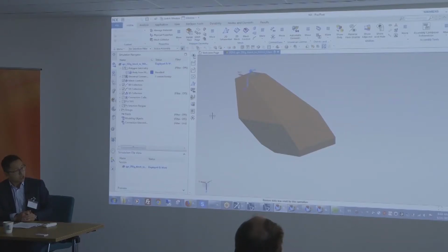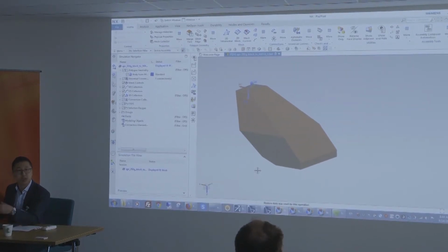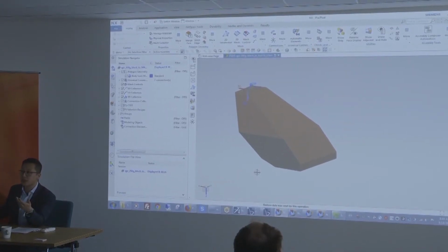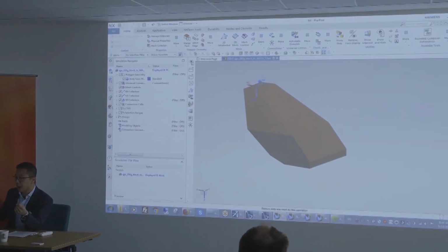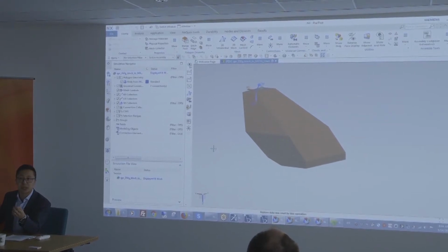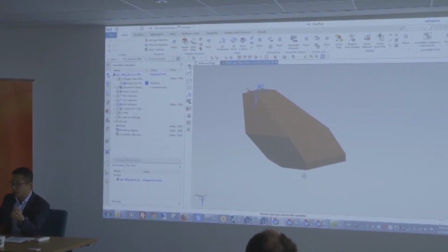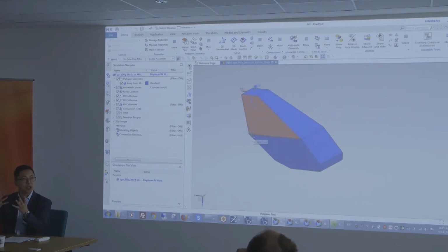All right, this is the FEM I've been speaking about. I'll go to the simulation part afterwards, where I define the boundary conditions and the loads in just a moment. But in this case, the objective is to use topology optimization to design a space bracket. This is my control volume. If I hide the mesh to show just the geometry, this is the volume within which my bracket needs to stay.